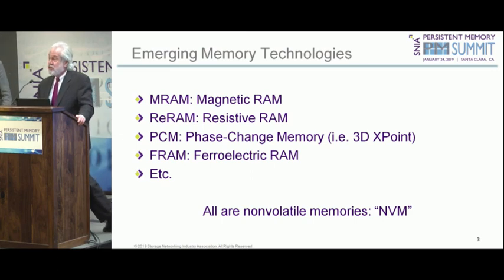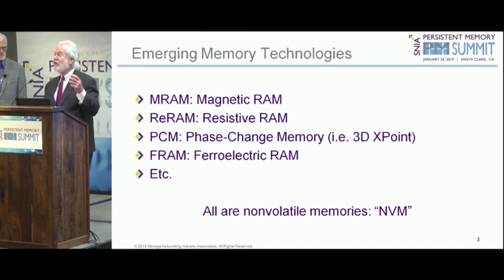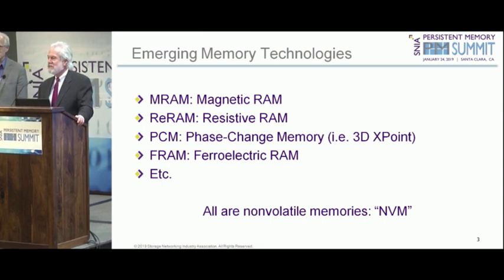And then you've got phase change memory, and that's the basis for the Intel Micron cross-point memory, which is used in Intel's Optane products and Micron's QuantX. Phase change memory is based on a glass, which if it's frozen slowly, crystallizes. If it's frozen quickly, then it's in an amorphous state. The amorphous state doesn't conduct, and the crystalline state does, so that's also a resistive RAM.